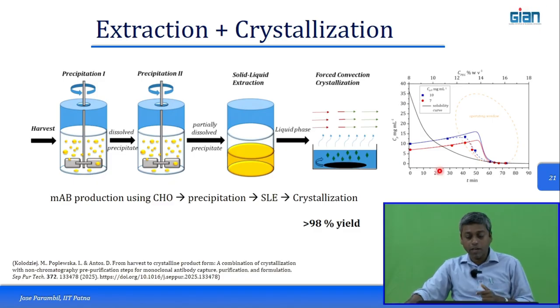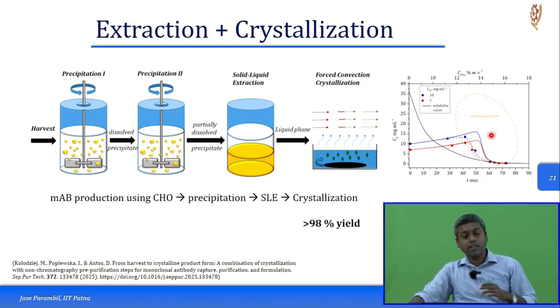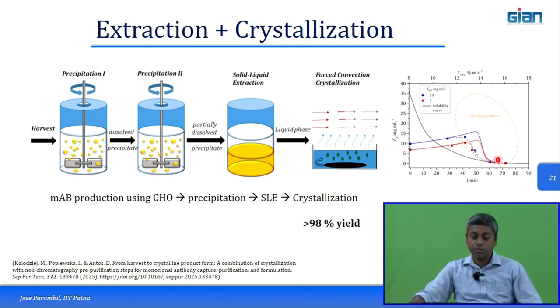And again, going back to the phase diagram, you can figure out where you are starting, how you can move, how you change the concentration during the process, and basically how you achieve control over the crystallization. So the process itself can be overlaid onto the phase diagrams in order to ensure that you get the right type and quantity of the crystals being produced.